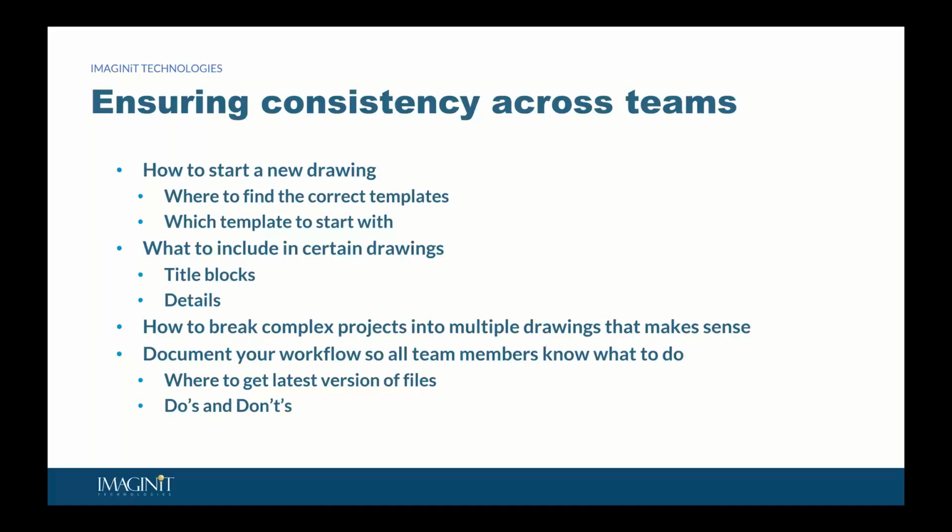So those are the things that I typically like to do. And again, do's and don'ts. Certain things to avoid: if you guys are running in a SharePoint or a Microsoft OneDrive environment, don't put your drawings in there. That's going to create problems. Maybe not now, but it will create problems later on down the road. Just be aware that those are not actually supported by Autodesk. They're considered third party because all of Autodesk's products do file locking and handle the save process and everything like that using Microsoft SMB protocols. OneDrive and SharePoint do not use those, so it's not considered supported, even though people do it.